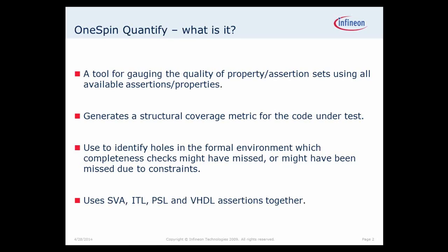It's basically a tool for gauging the quality of your properties and assertions using all of the available properties and assertions you've got. So if you have assertions embedded in the design as well as a handcrafted property environment, it will quite happily run them all, whether they're in PSL, SVA, the in-house ITL language, VHDL assertions. So if they're there, it will use them. And basically, it generates a structural coverage metric for the code under test.